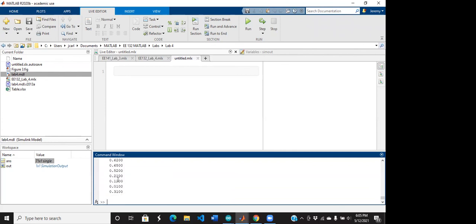And something to remember is that because we're having both these 2 workspace blocks sample at the exact same time, the time vector of timestamps you get from one of the 2 workspace blocks will be the exact same as the one you get from the other workspace block.